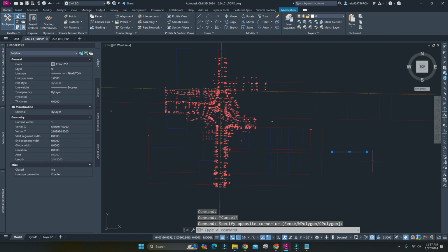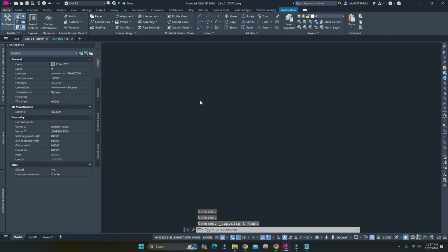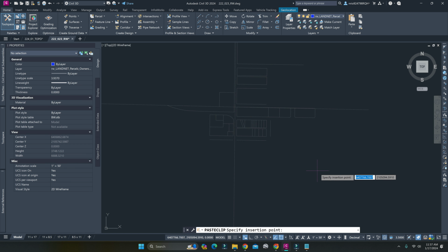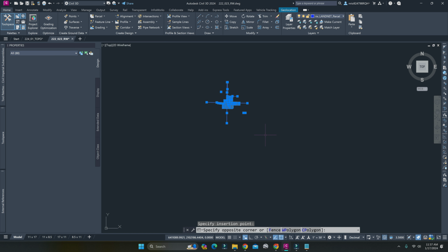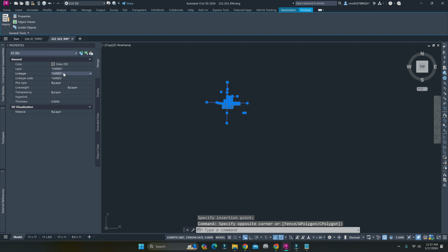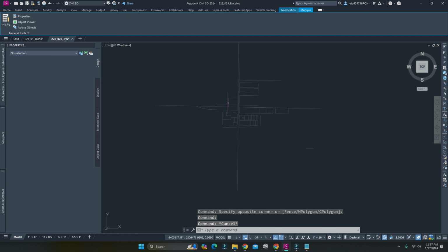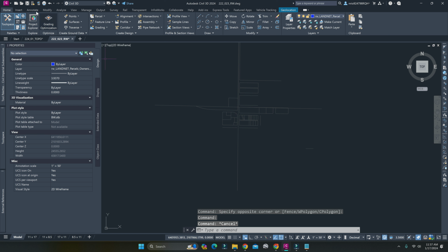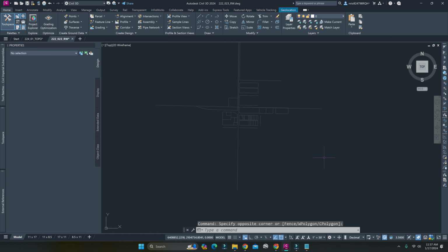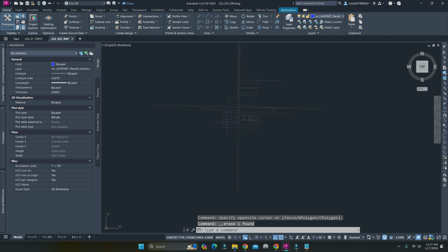And I'm gonna pick that up, copy it, bring it over here, and I'll paste it here, and then I should be able to change the line type, do a phantom, and then I'm just gonna hit save on that, and it should show up over there like that as well.